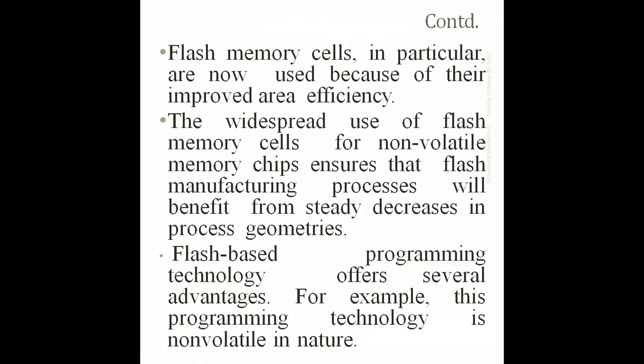Flash memory cells are now particularly used because of their improved area efficiency. The widespread use of flash memory cells is for non-volatile memory chips, ensuring that the flash manufacturing process will benefit from the decrease in process geometry. Flash-based programming technology offers several advantages. For example, this programming technology is non-volatile in nature. The basic thing is flash memory is non-volatile in nature.